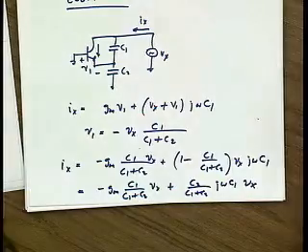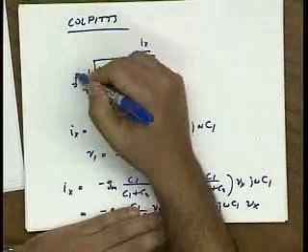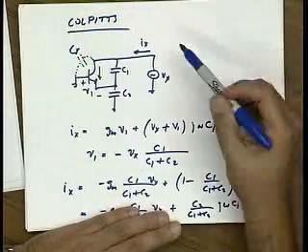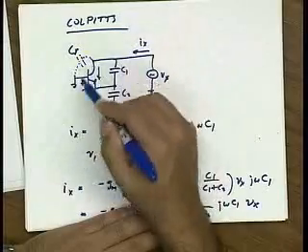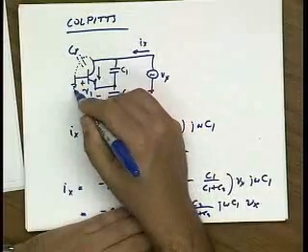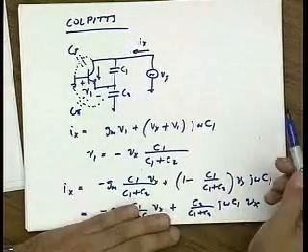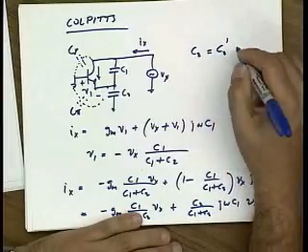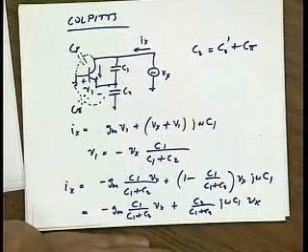Also, another observation here is that this transistor has some capacitance that's going to affect these calculations. In particular, it has C mu, but C mu just looks like a capacitor in parallel with our load, right? So I can just neglect C mu and put it in shunt. That's negligible. The other capacitor is C pi, and C pi can just get absorbed into C2. So really I could say C2 is equal to C2 prime plus C pi. Okay? And then I can just assume this transistor doesn't have any capacitor parasitics.